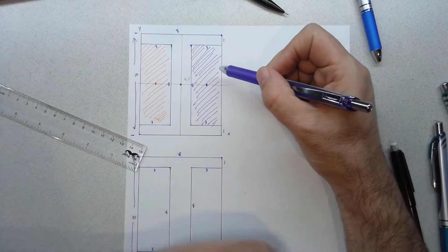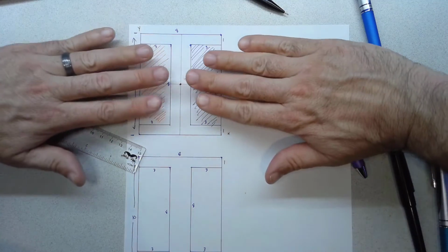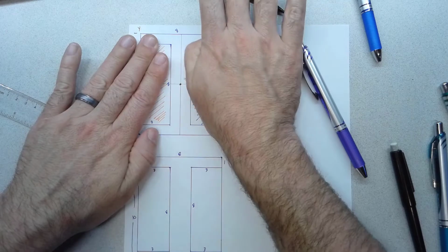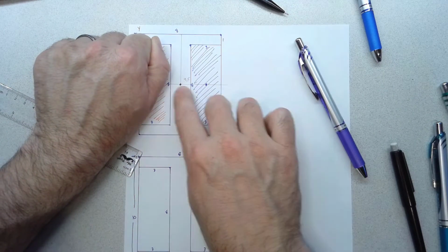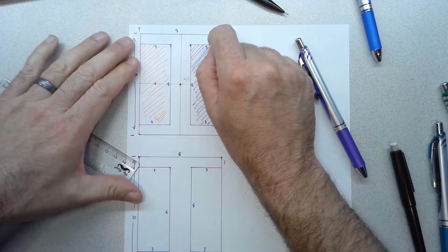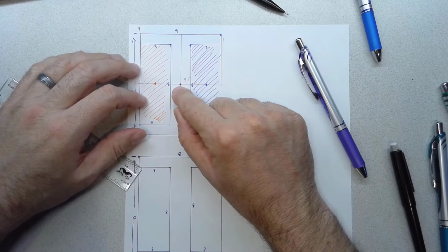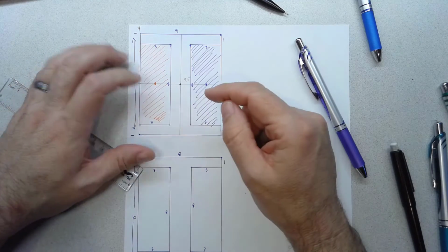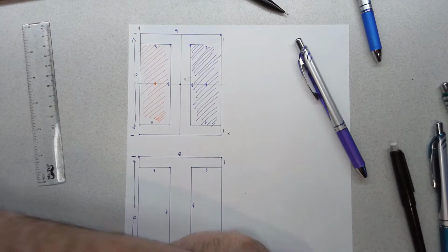And since after we subtract those out, the centroid of this I shape, basically if these pieces are gone, hopefully you can see they're still symmetrical about these two axes. So the centroid of the final shape is no different than the centroid of the original rectangle. And that makes it simpler than what we're going to do later on if we look at a different shape.